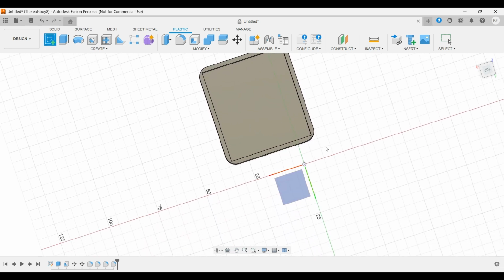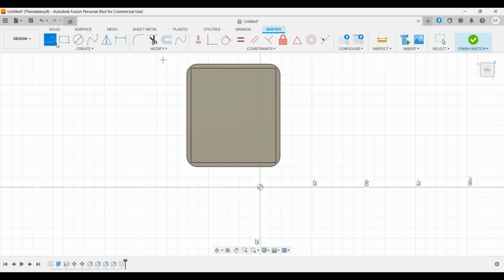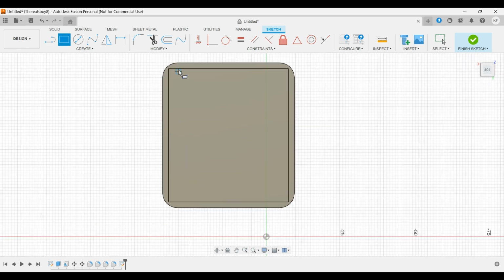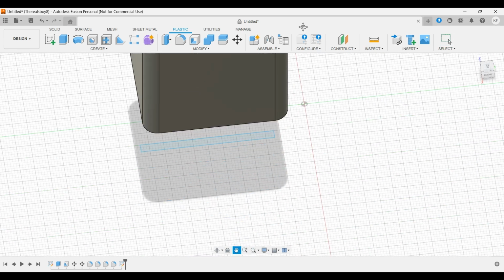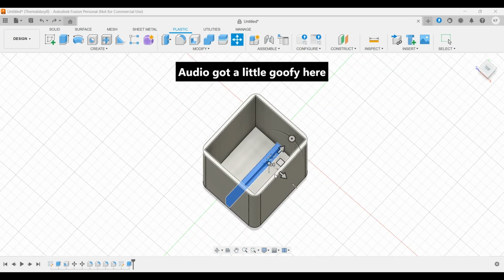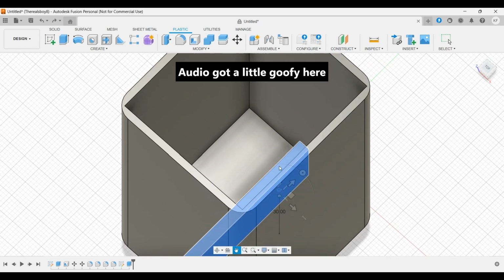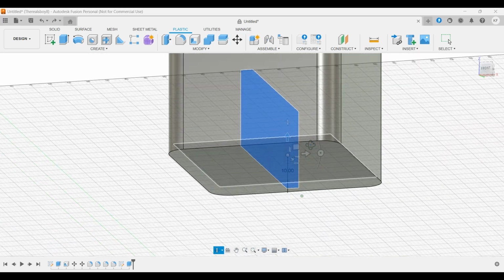And here's where the axis is really coming into play. If I go like this, then I can go directly here, take this little 2-point rectangle again, and say I want it to be in the middle, right? I go all the way down like this, right? Press finish sketch. Take this, which should be actually underneath here, and we're going to extrude it, bring two things together, then Fusion will automatically say that these two things are now one thing, and you can't move this one part anymore, as long as they're touching.